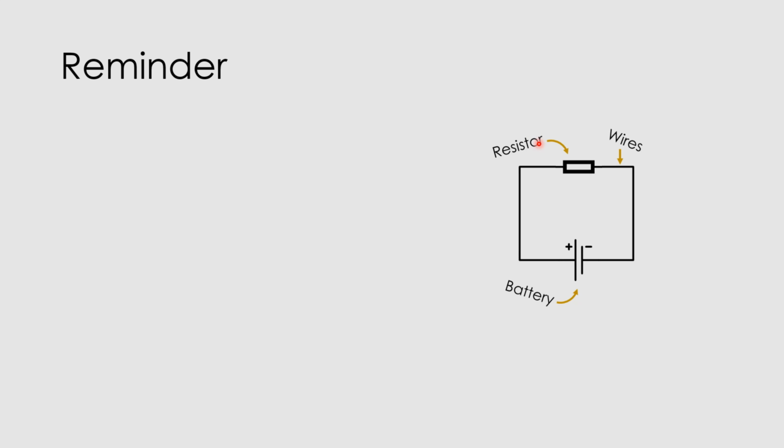Typical questions you might be asked at basic electrical principles level courses will include things like denote the difference between conventional current flow and electron flow, or explain the difference between them using the aid of a diagram, and so on. In that case, you draw something that looks a bit like this, and as a reminder, conventional current flow flows from positive to negative. We think of it as the positively charged particles flowing from positive to negative, as denoted by our little red dot here moving around the circuit.